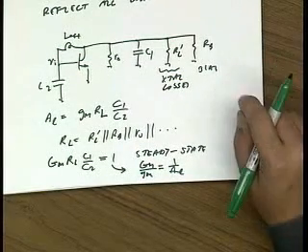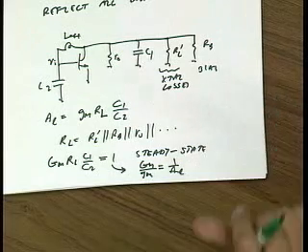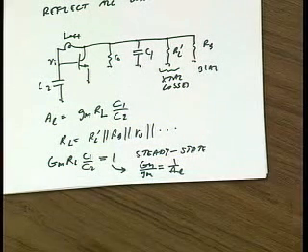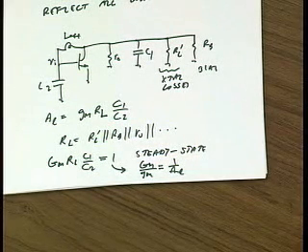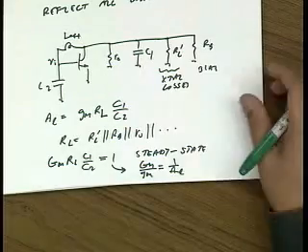With the Pierce, you can play some tricks. You have to introduce an external tank to artificially kill the loop gain at low frequency and allow it to get high at the frequency of interest. But you're going to end up loading the circuit a little bit. We'll look at another circuit that has less loading. Yeah, we'll get to it.